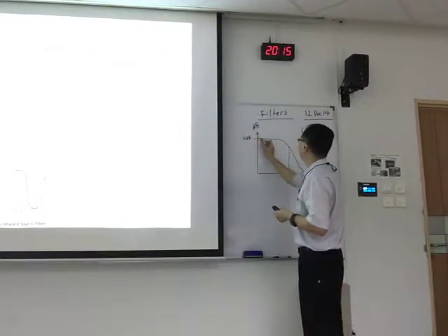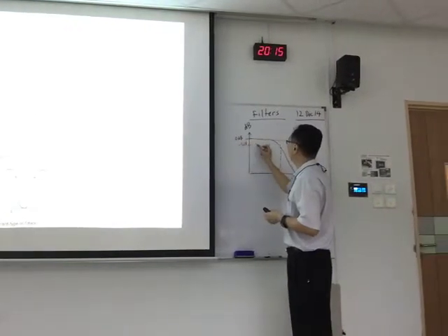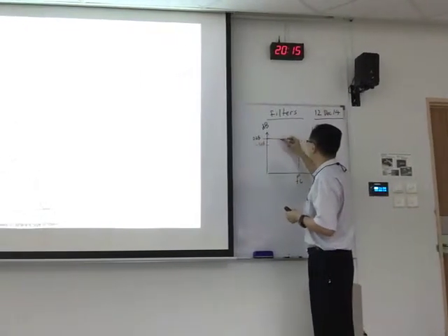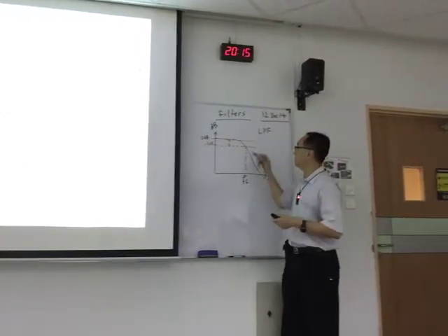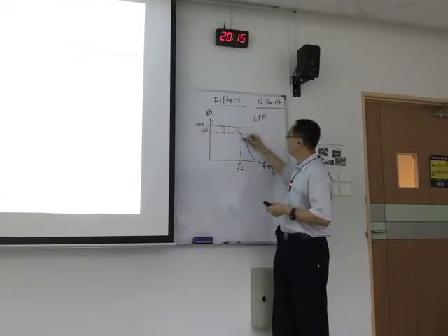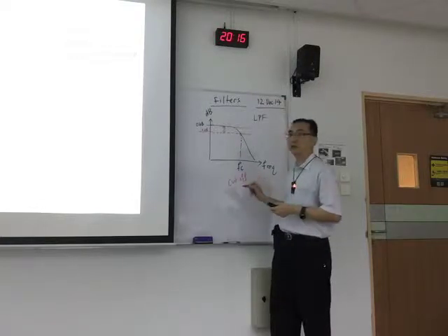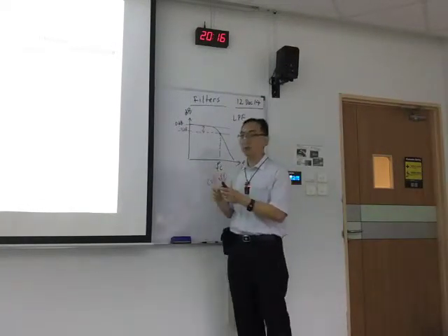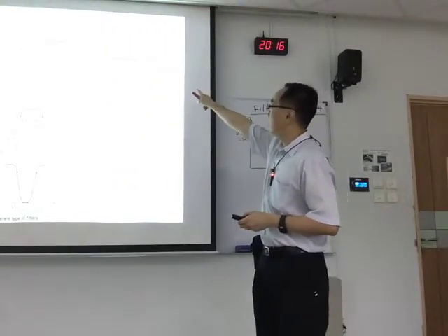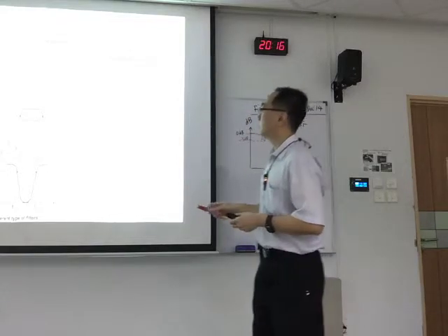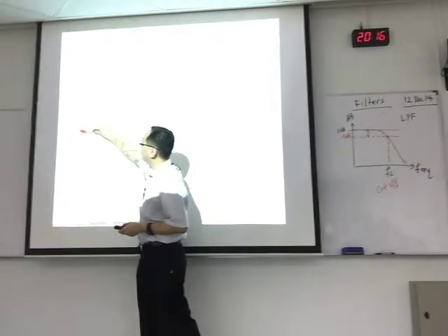From this 0 dB line, you will drop by minus 3 dB, then you intercept the curve, and you draw a line down here. This is the cutoff frequency. This is standard: minus 3 dB is a standard figure. You can read your notes there. If you look at your notes, here is the 0 line, 0 dB, and you will drop by minus 3 dB.